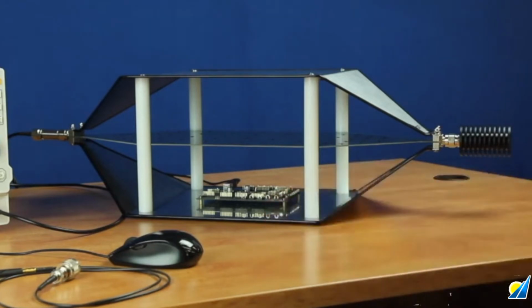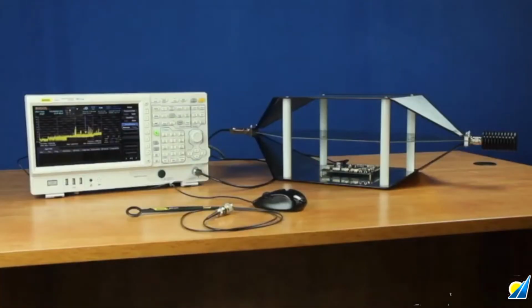In an open TEM cell this size, the general rule of thumb would be emissions above about 40 dB microvolts are really areas of interest or concern for our ongoing testing. So we can do this setup in any kind of a room with our spectrum analyzer where we can start to see emissions in a radiated sense to validate.